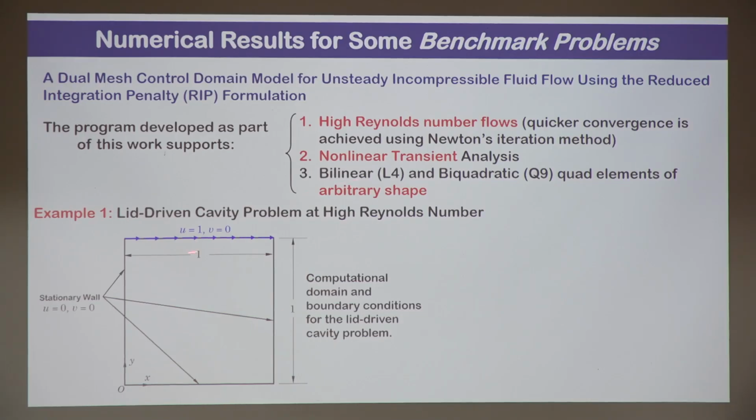Of course, it is all a non-dimensionalized problem. So if this U is increased to a large number, that means the Reynolds number will increase. I'm showing you this just as an example here. You can see the corners will have a singularity, correct? Because we are saying U is equal to 1 from this side, but from this side, U and V are 0. And that is where your real world thinking has to come.